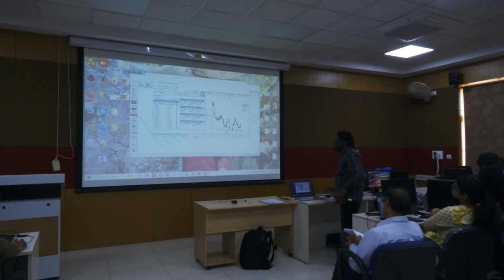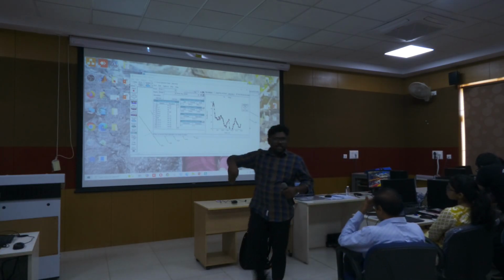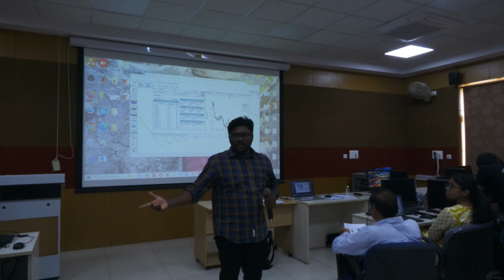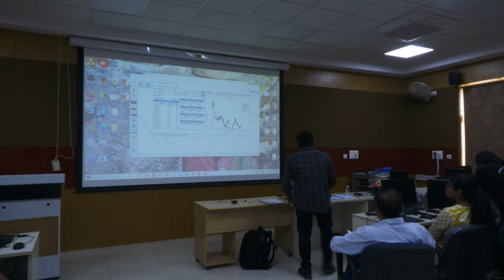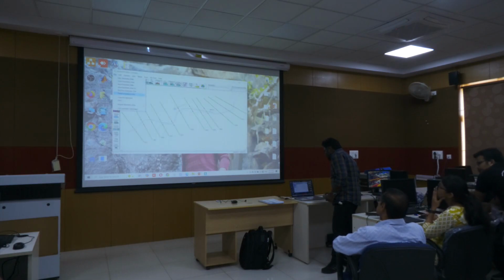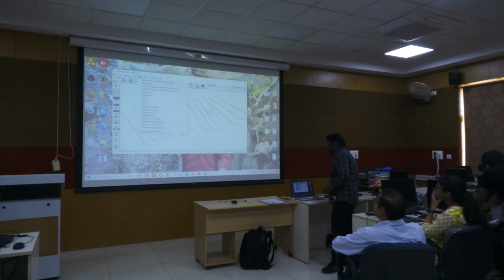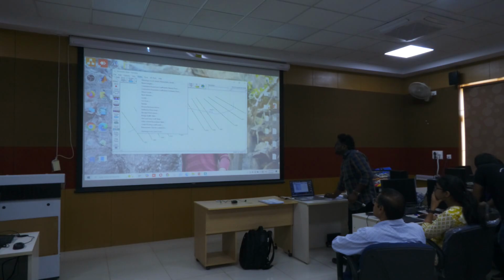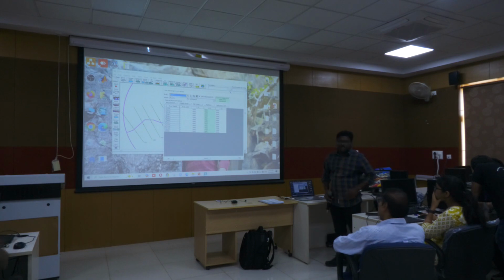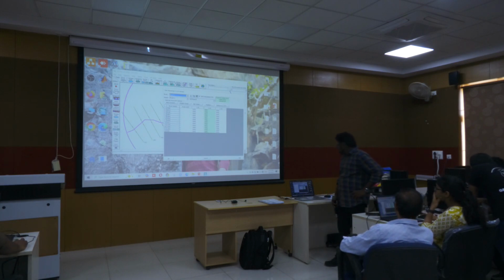So next step is, we have removed this horizontal variation along the cross section, but we have to provide the roughness value in the main channel and the floodplain. Okay? Just save this geometry, and click on tables. Click on tables, and click on Manning's n value.